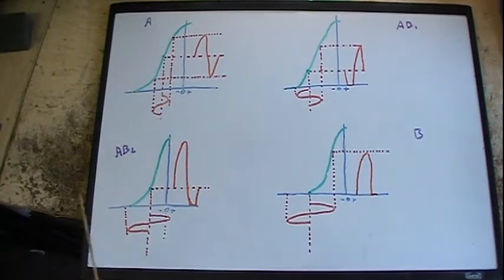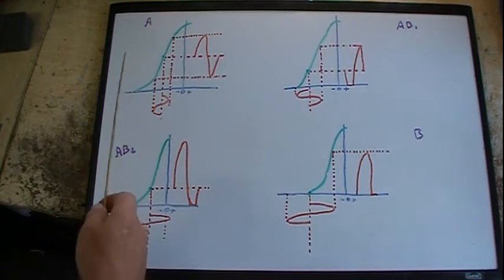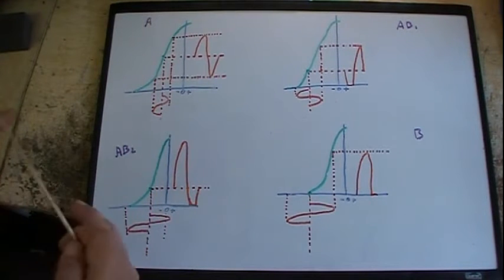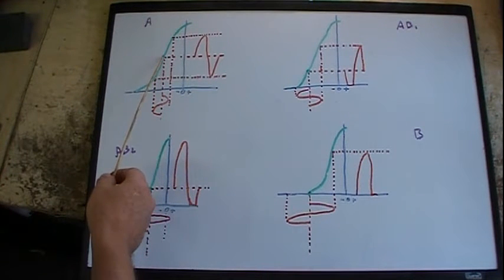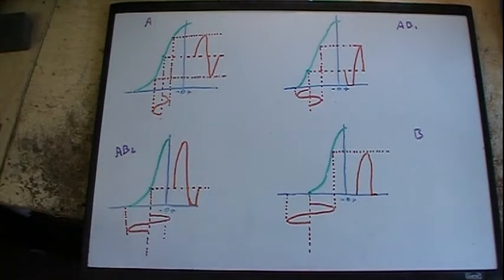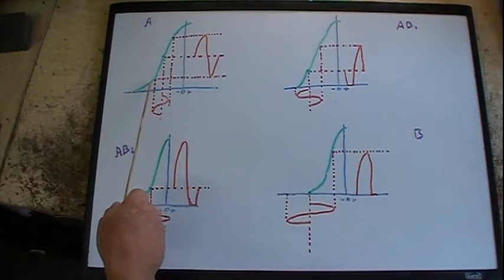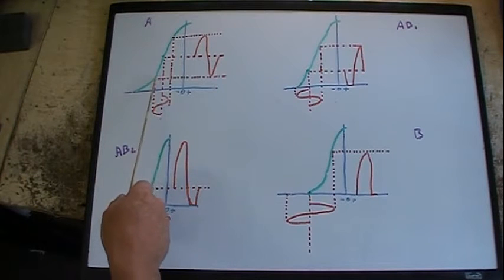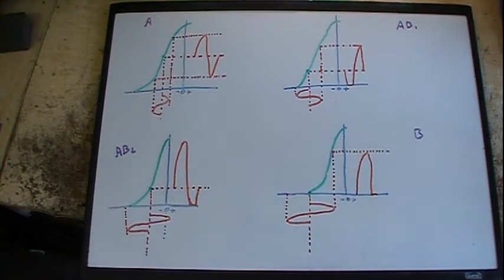It's Class A. But if you're designing one and wanting to have it operate with the least amount of distortion, you center your operating point on the linear portion. And except for the very strongest signals, it will operate with virtually no distortion whatsoever. Now it can get down in what they call the knees, the bends of the curve, and that's where you start getting your distortion from.